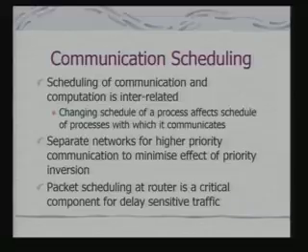But scheduling of communication and computation is interrelated. Changing the schedule of a process affects the schedule of processes with which it communicates, because that process cannot start until and unless it gets the data from this process. And you may need to take care of the delay because of priority inversion, so use separate networks for high priority communication to minimize the effect of priority inversion.